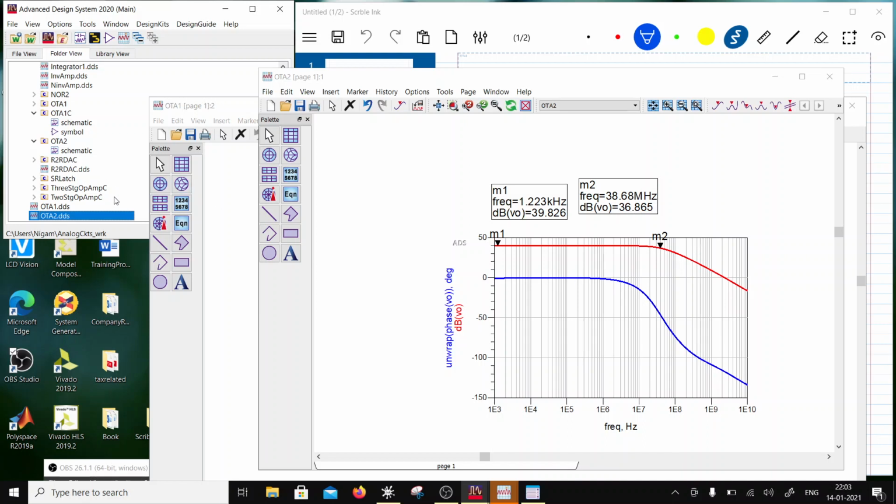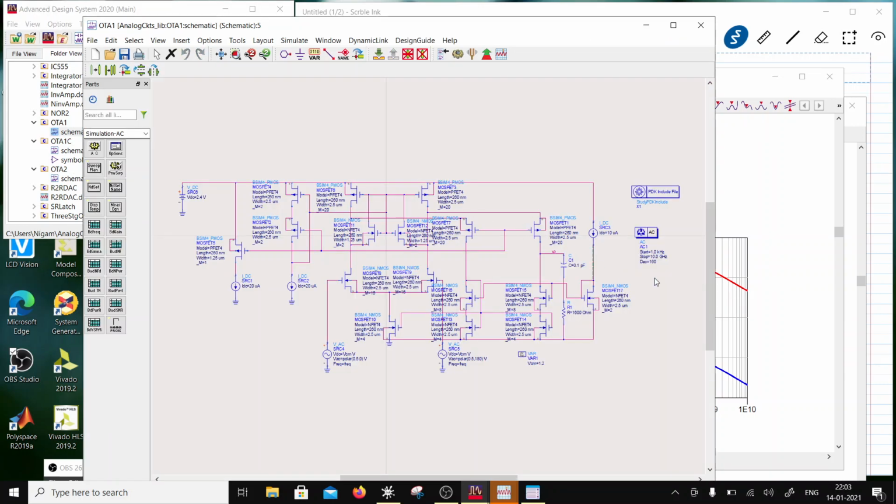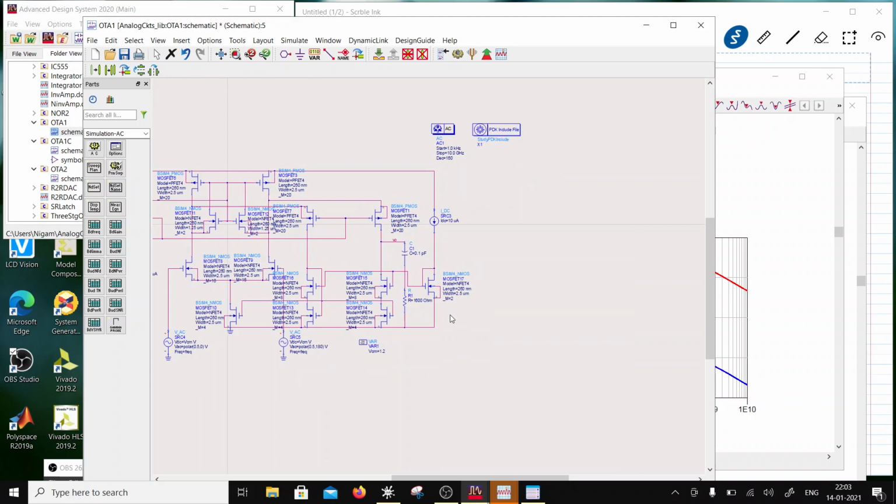Now both of these, right, they don't have an output stage, so if you want to use them in feedbacks, resistive feedbacks, you won't be able to use them. So if you look at OTA1, for example, we made a component of it, right? So let's look at OTA1. So in this case I would have to add here a source follower, right? And that source follower, right, would be a PMOS, because the output here is a NMOS. So there will be a source follower, right?